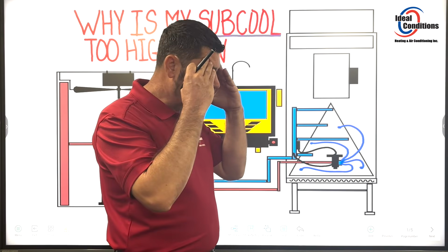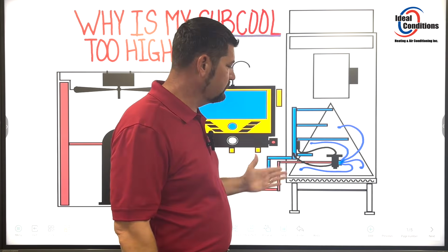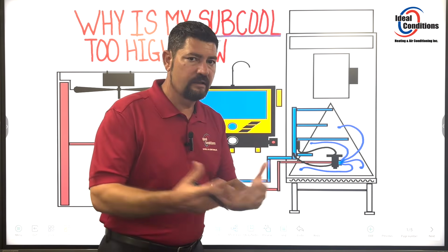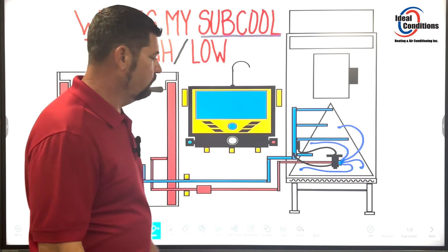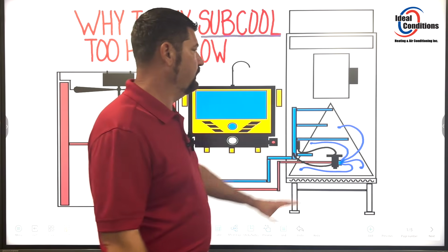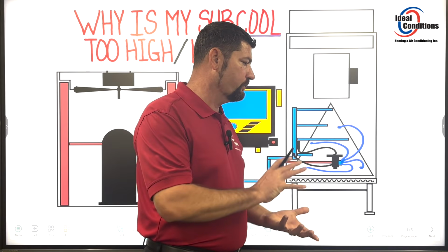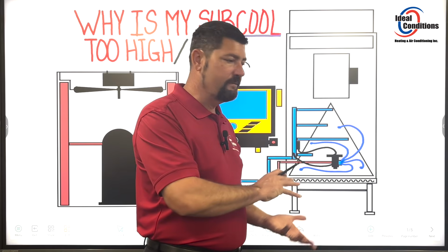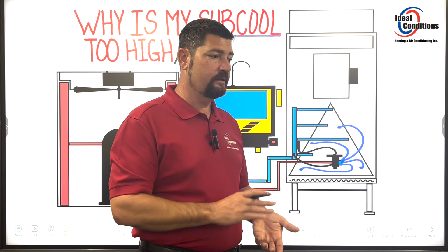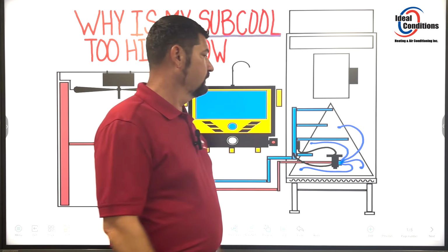And you wonder, like, why are my motors failing? Did you ever put the right CFM back into it? Why can't I get the right superheat and subcool? Is any of it in the design? No, you've altered it too much. Put things back to where it's supposed to. I'm not saying you got to go back with the manufacturer's exact motor that you bought off of their shelf that they manufactured and overpriced and sold you. I'm just saying that be within their specifications, their guidelines. All right?